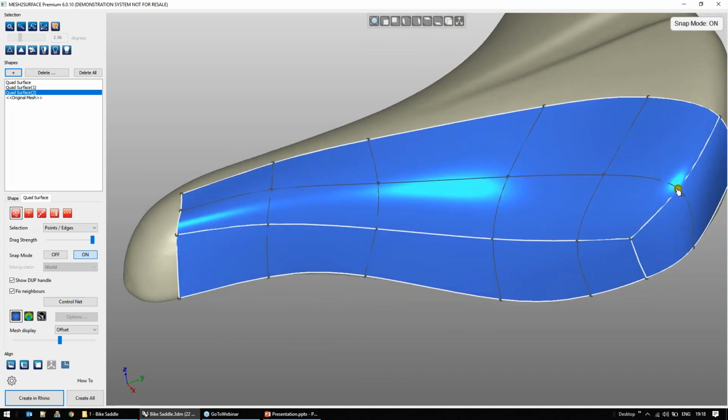Why do we see these white and dark lines? When you have faces during your building process, the software tries to create patches which will actually be a single surface. This means that when we create a NURB surface, it will not have as many NURBs as faces, but the software automatically tries to combine the surfaces. In this case, we'll have only 3 surfaces.